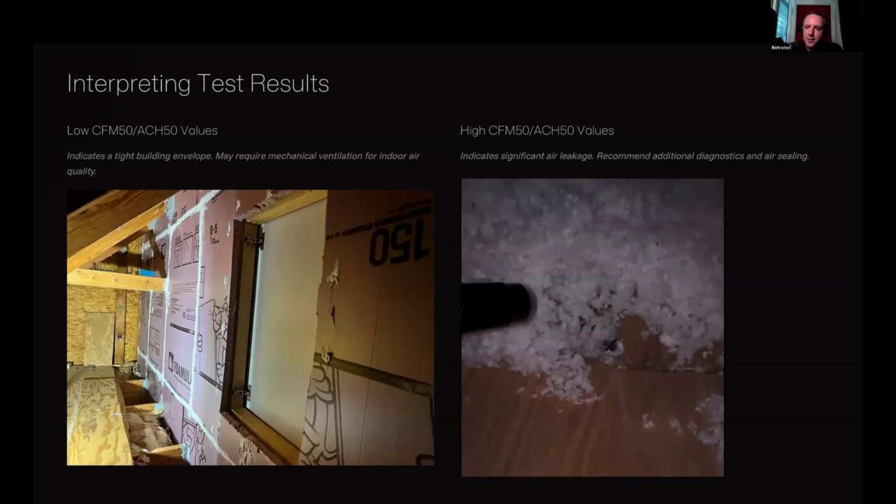Yeah, and there's a program you can download off our website too called Virtual Gauge. And it's basically just the interface of our DM32 previous manometer. We haven't quite updated it yet for our current manometer, but you can still use it. And basically, you can put it in simulator mode and then just fine tune it to replicate what you did in the field. And so if you chose the wrong range, you can put what you did in the field, go back, change the right range, and it'll give you the correct output. Or same thing with the volume.